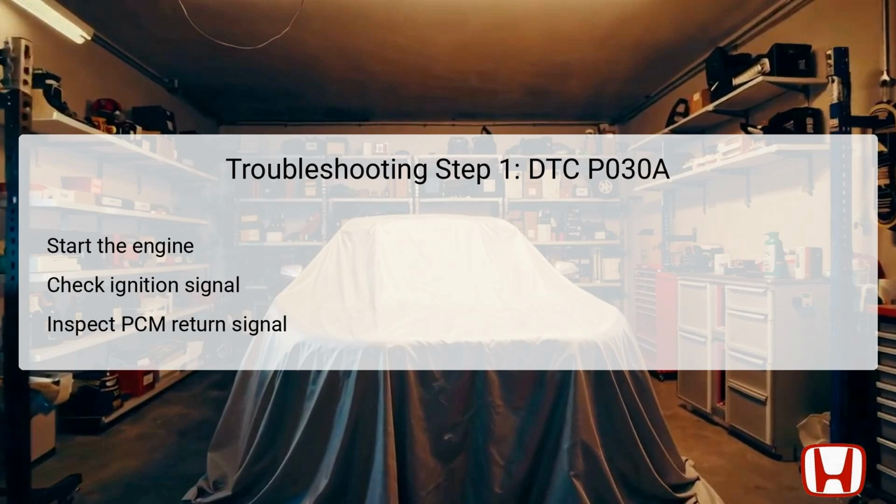The ignition signal produced by the ignition coil, which is represented as an electrical pulse, needs to be verified for proper operation. The PCM, being the central monitoring unit, continuously checks the return signal from the ignition coil to ensure it falls within expected parameters. If the return signal does not vary accordingly during ignition events, this points toward an abnormality in the circuit, necessitating further inspection.